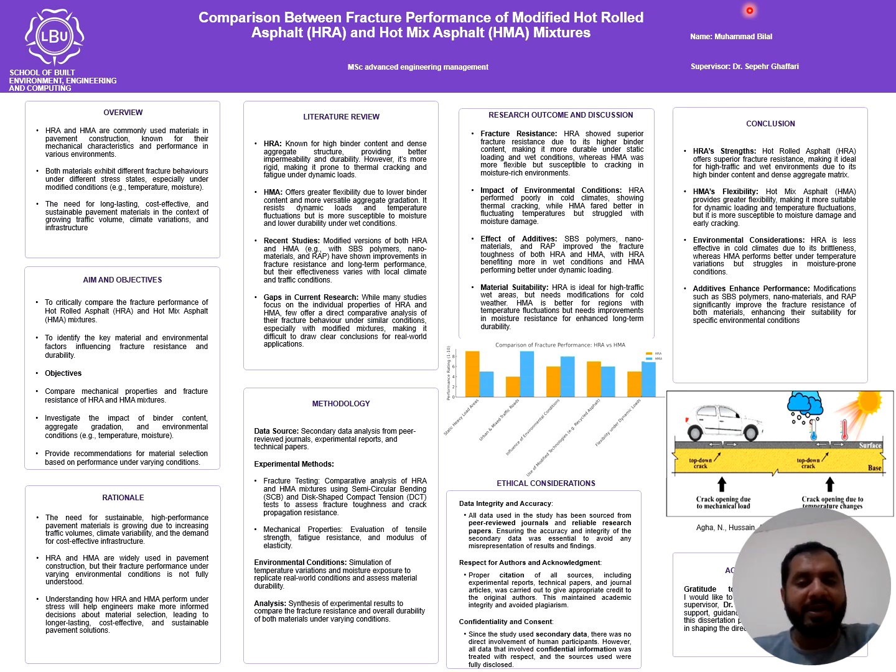Here are some recommendations. Use fibers, hydrated lime, and polymer modifiers to improve aging and cracking resistance. Apply fracture-based testing standards like IDEAL-CT and SCB IFIT for better quality control.